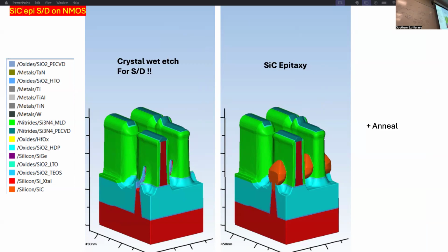Why do you need to do that? Because I still haven't put my high K dielectric. Everything here is still some oxide, nitride. Once you put your high K dielectric, you no longer can put polysilicon, because polysilicon is a high temperature process, and the moment you do a high temperature process after putting a high K, it's going to damage the high K. So everything after the high K is a low temperature process. That's why I use a metal, because metal can be deposited using PVD, sputter, which is a low temperature process.